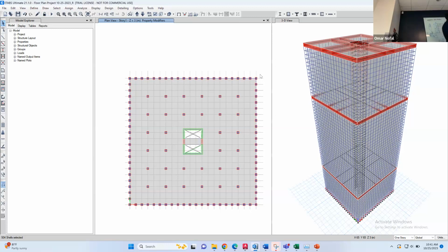The second one, assigning diaphragm. If you didn't assign diaphragm, your model is going to run forever. Why? In lateral load analysis, we don't care about the slab bending, or what is gonna happen to the slab in the floor. We only need from the slab its weight as a mass, and how much it is gonna be pushed away from the building, making straining action on the columns.